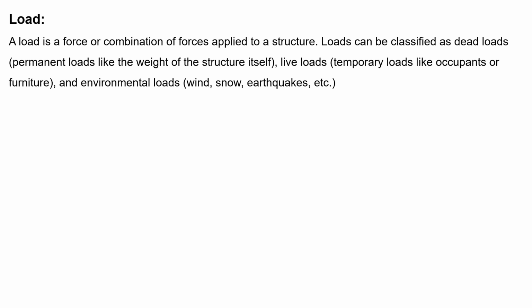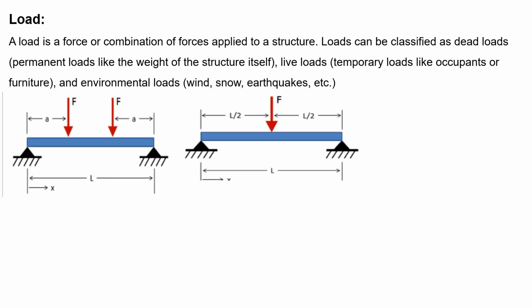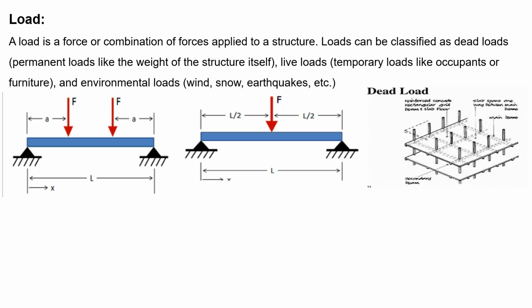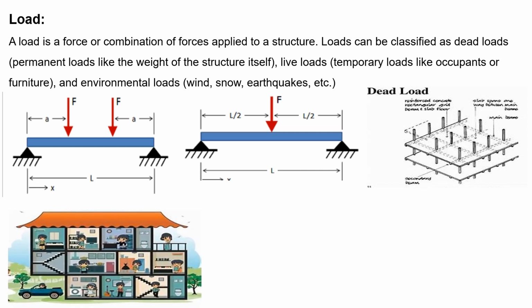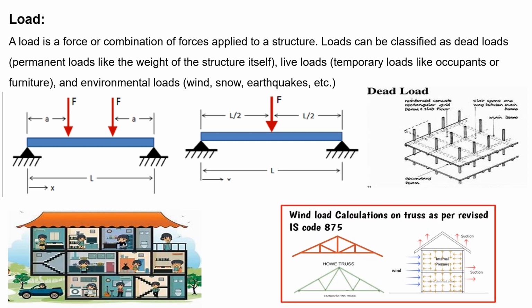2. Load. A load is a force or combination of forces applied to a structure. Loads can be classified as dead loads, permanent loads like the weight of the structure itself, live loads, temporary loads like occupants or furniture, and environmental loads, wind, snow, earthquakes, etc.